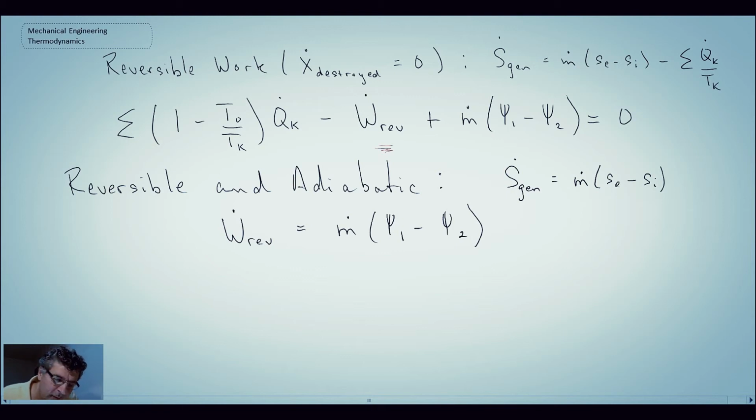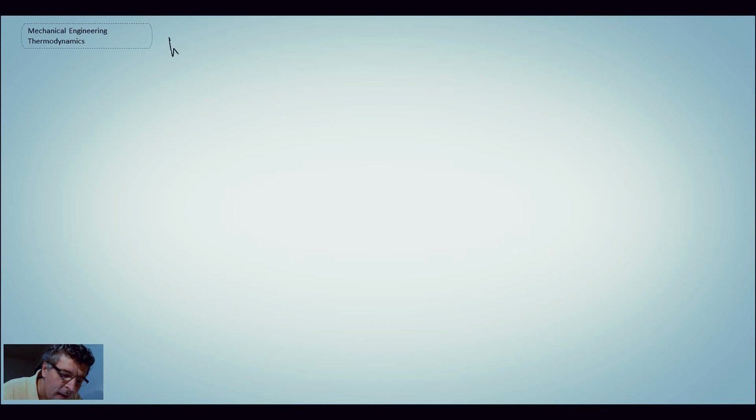If we further neglect kinetic energy and potential energy, what we end up with is the following relation. And what I'm going to do here is expand out the exergy change term that we have for an open system. Oops, sorry, the first one, that should be S1 minus S2.